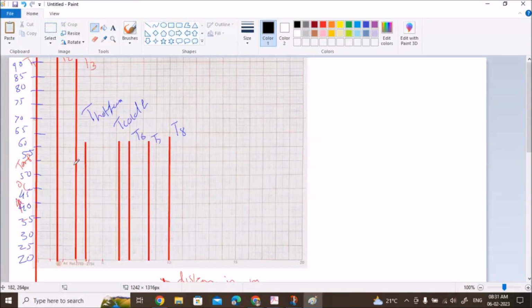Now first temperature is 52 point, so 52 point is somewhere here, 50.8 is somewhere here, 49 point somewhere here, then 26, this is 25, T6 is 26 here, 2 lines, then 25, 26 here, a small difference, 3 lines here and here 2 lines, and then 23 here. So 23 means 6 lines here. Yes. Join point T1, T2, T3 and extend it up to T hot face.